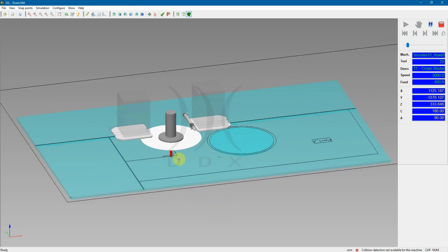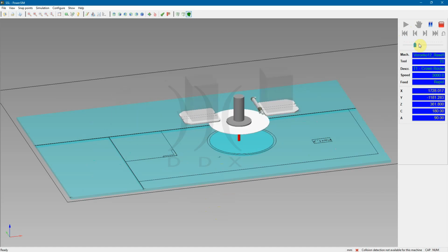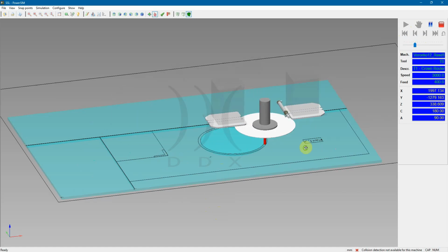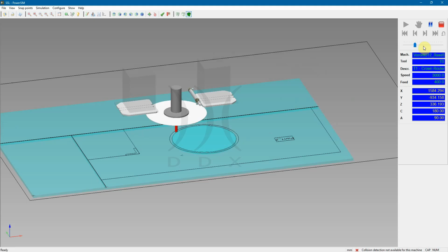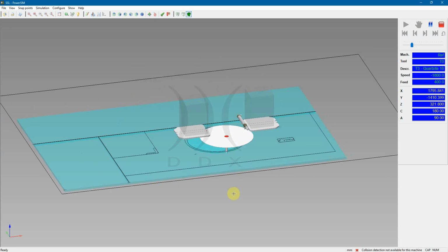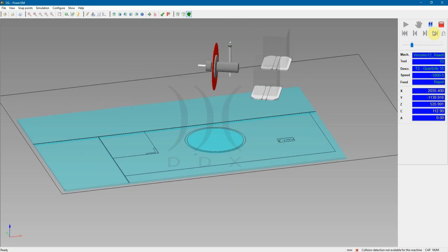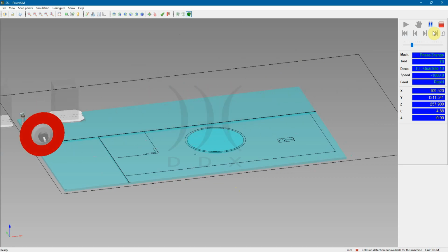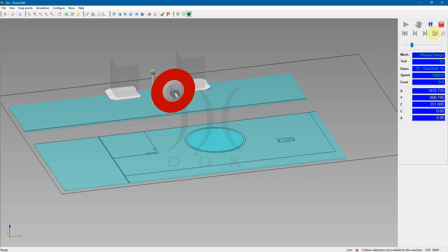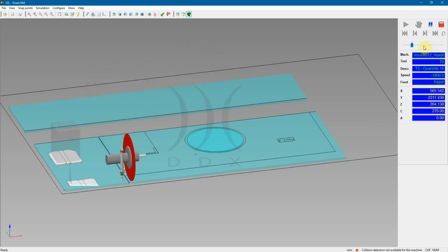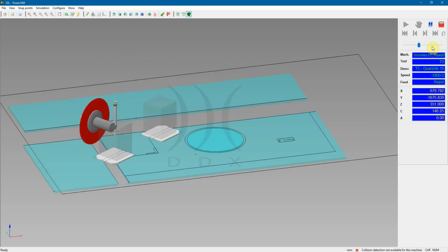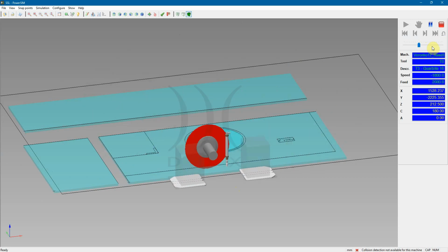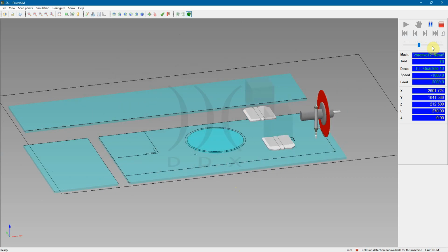You can see how it starts with the center milling tool. Once the milling tool is done, it changes state. So now it's working with the saw blade. Makes vacuum movements as needed. And then I'll continue cutting until complete. That's my brief demonstration of how to use nesting with a 5-axis bridge saw.